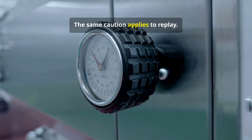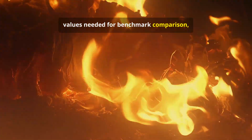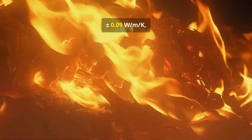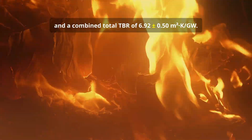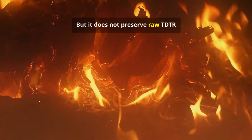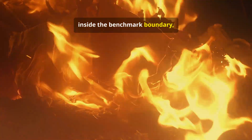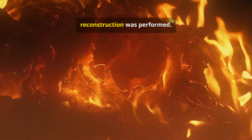The same caution applies to replay. This packet preserves the key reported values needed for benchmark comparison, including the two XRR thicknesses, an intrinsic Al2O3 conductivity of 1.50 plus or minus 0.09 W/mK, and a combined total TBR of 6.92 plus or minus 0.50 m2K/GW. But it does not preserve raw TDTR delay time traces for replay. So this lesson can teach route ranking inside the benchmark boundary, but it cannot honestly speak as if a full trace-level thermoreflectance reconstruction was performed.